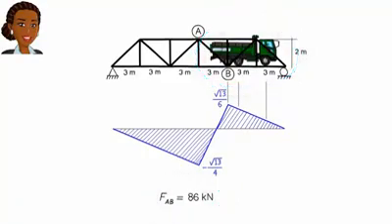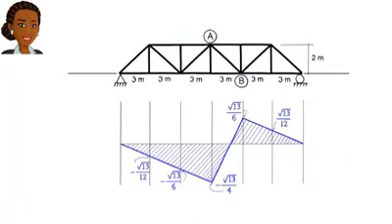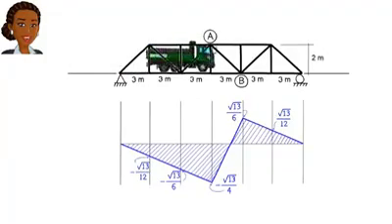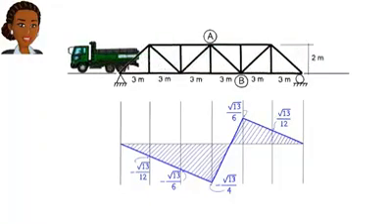In summary, when we have a moving load series acting on a truss structure, we need to investigate all the loading scenarios that potentially could produce the largest axial force in the member under consideration. This means we need to move the load series in both directions, up and down the bridge, in search of the critical locations. Here are a couple of exercise problems.